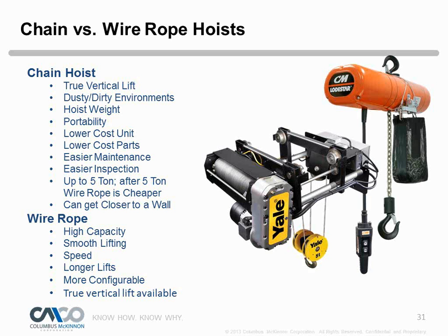The wire rope hoists tend to get better speeds than chain hoists because, especially in the higher capacities, the chain hoist has multiple reevings, so it really slows down the electric hoist because we have to overhaul all that chain. So the wire rope hoist will start exceeding the speeds of chain hoists in certain applications.